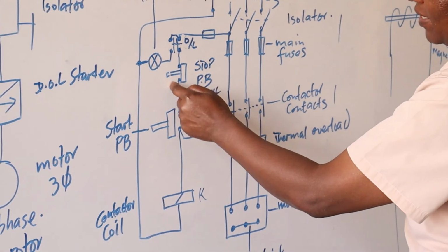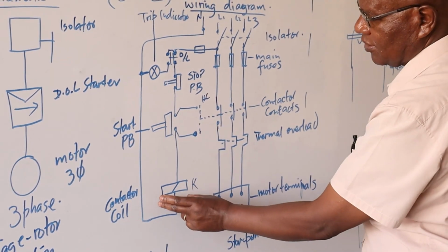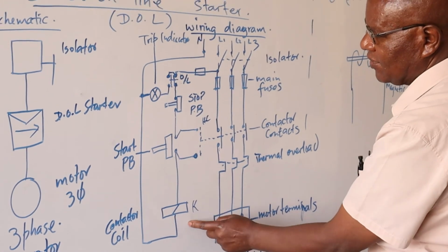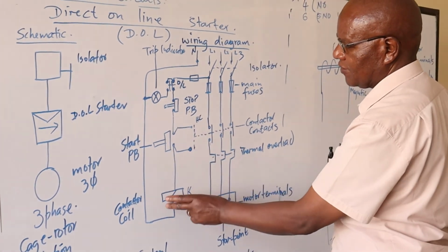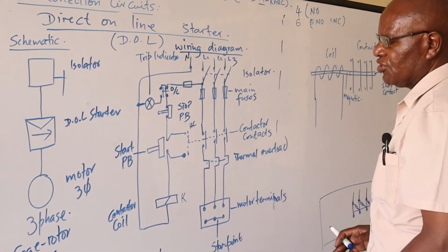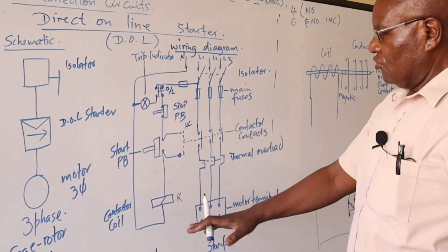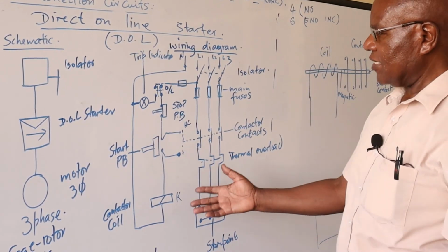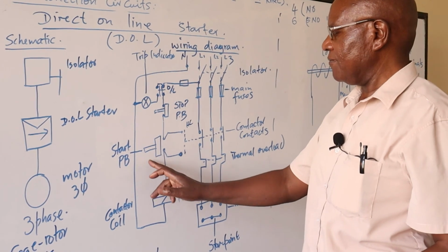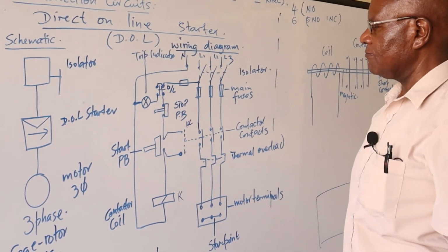But then when it comes back, you'll find that the motor cannot restart because this cannot be energized. There is no path for it, fulfilling one of the IE conditions that the motor should not automatically restart until you start again with a push button.